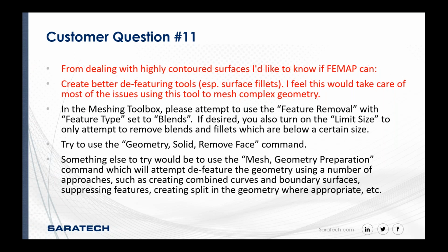Now you can link the amount of geometry preparation to the mesh size. You can raise the preparation size, so it's going to find more and more features to try to remove or defeature a little bit, and then size it with something smaller if you like. So there's a lot of options in here, honestly. So again, just maybe give it a try.